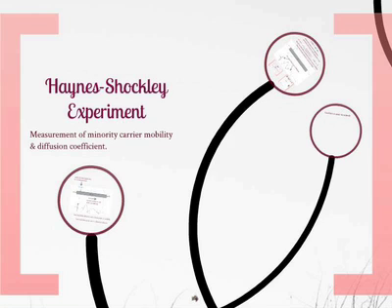The Haynes-Shockley experiment is the analog for the minority carriers. So it's a bit more complicated. It's not as simple as the Hall effect. The Haynes-Shockley experiment is also very important historically, and I've posted some extra material online so that you can take a look. Essentially, it allows you to calculate the minority carrier mobility and the diffusion coefficient. Recall that minority carriers can have a significant impact on current because they diffuse under concentration gradients, and the gradients can be quite large. So that's why we need to know this.